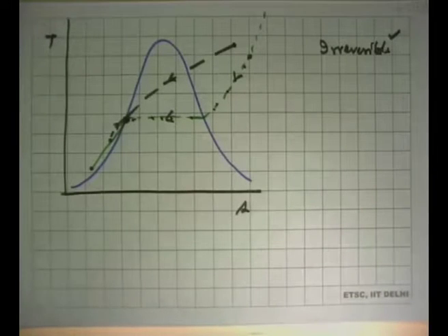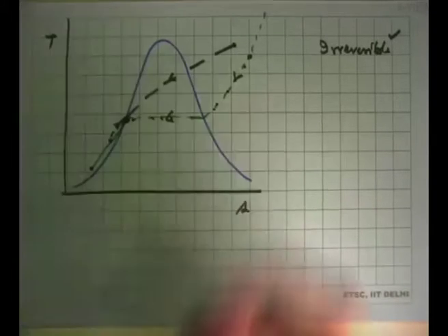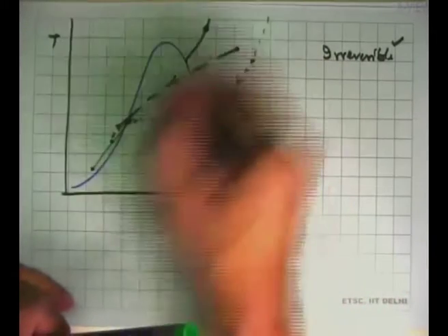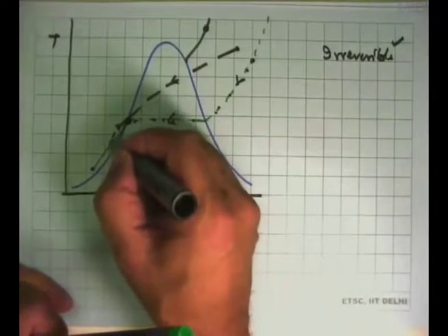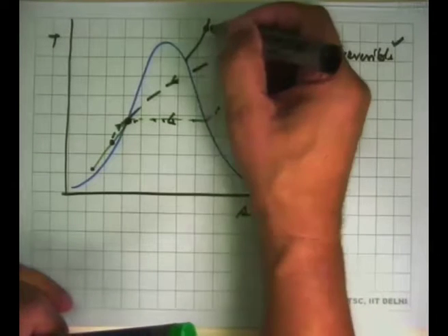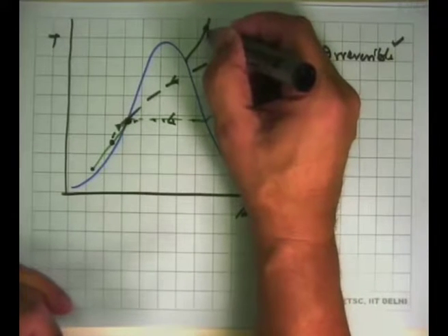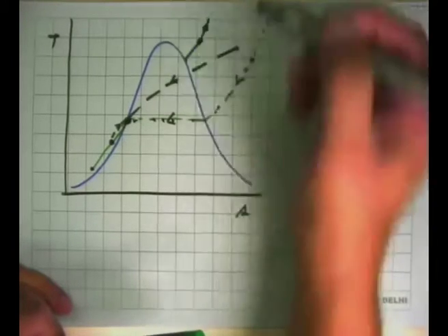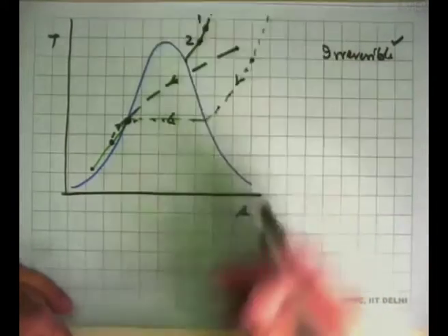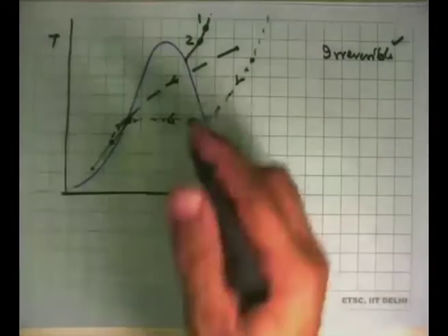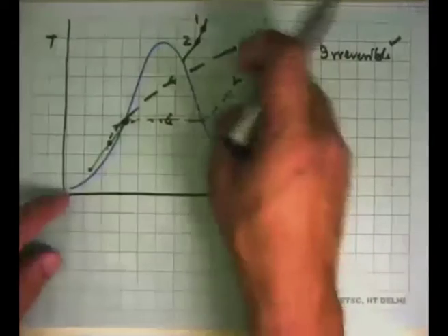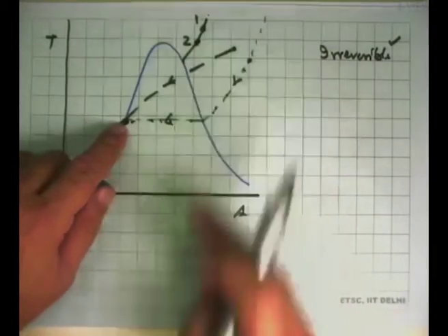In the case of the de-superheater, what we did, we had a superheated state here, and we mixed water with it, which was at, say, this state, to produce a state which is at the lower temperature but the same pressure. So we came from 1 to 2 by mixing things. So we moved from here to here and there to there, but in this case we have moved from there and here to this place.